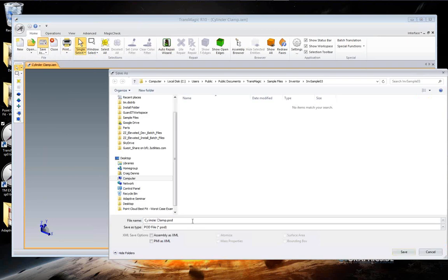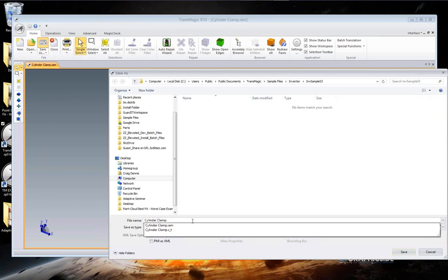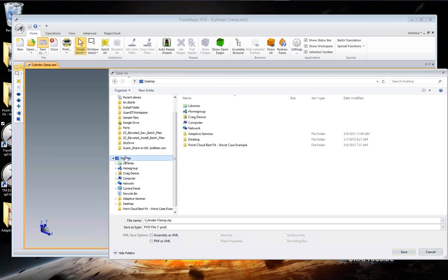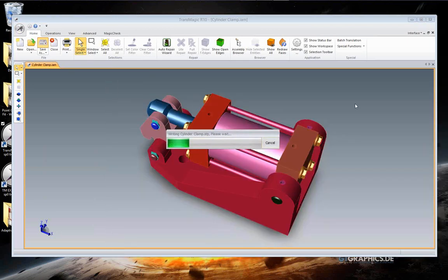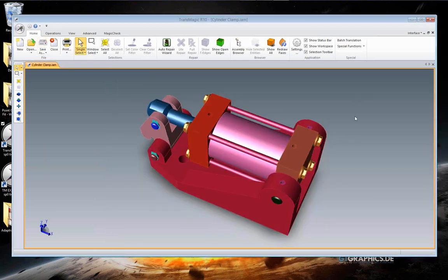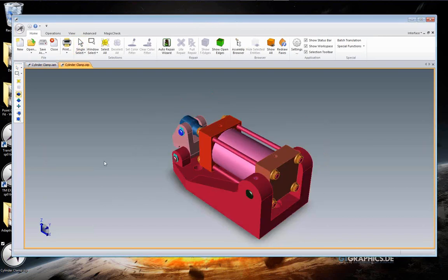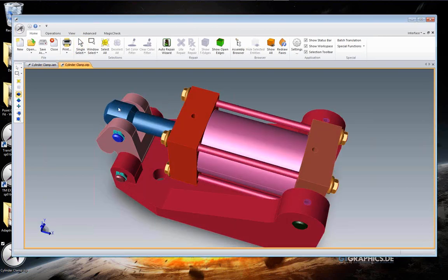And the formats that you'll have available are STEP and IGES. So let's save to a STEP file, put it on the desktop. Simple as that. So you've got a STEP and IGES output, click and drag interface, very Windows, very native. I'll drag it back in there. You could actually run a validation on those two parts. This is interesting. Notice the split cylinders just because it's a STEP. But that's an example of a STEP translation.